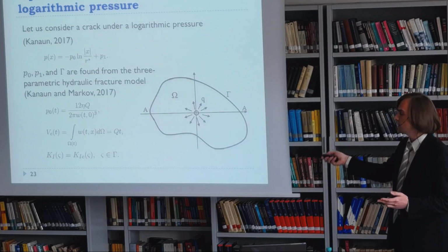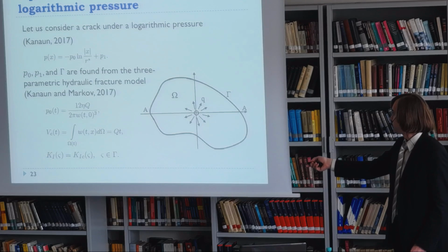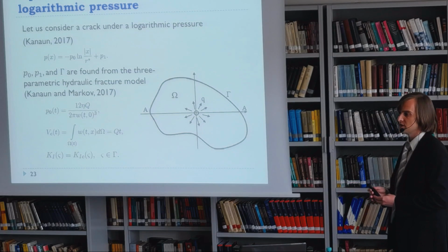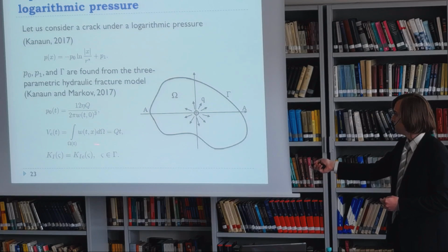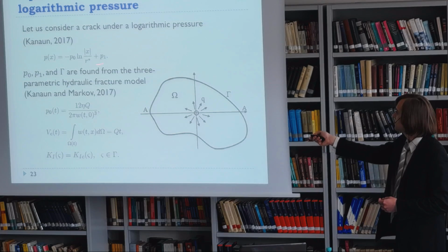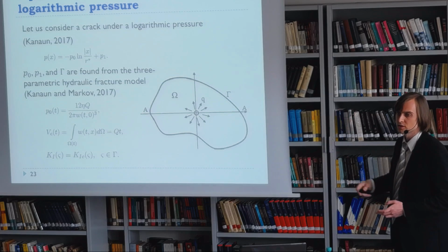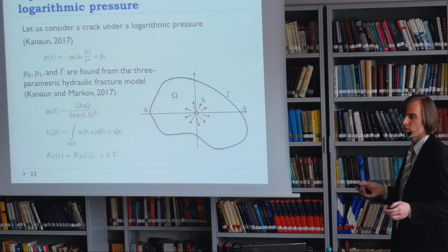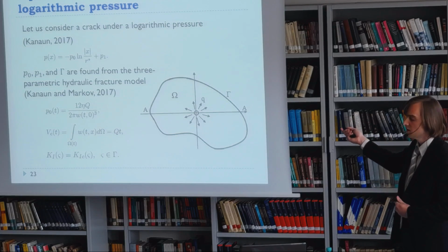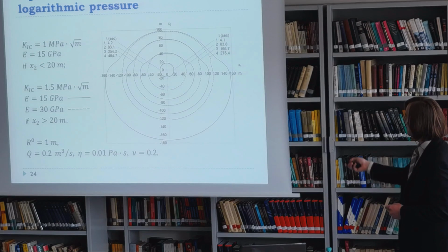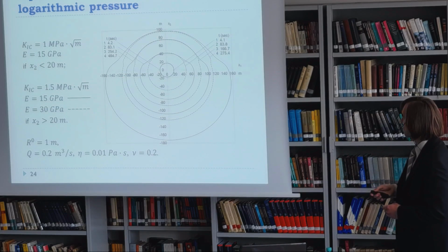So we simulate step by step, and at each step the stress intensity factor on the crack boundary should be equal to the fracture toughness, as I have mentioned previously. So this is what we should calculate by this numerical solution for each value of the pressure, which is found from these two equations. That was the goal of application of this numerical technique, basically. So we have to calculate this crack shape for this pressure, which is logarithmic. So here is an example of the crack growth.